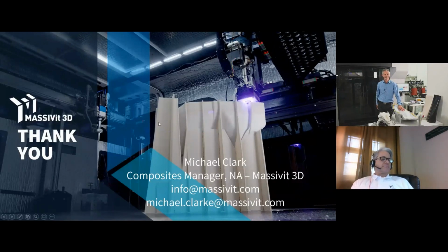Can you say anything about the tensile strength of the epoxy or its hardness, Barcol hardness? Not off the top of my head. We have them both in the tech data sheet, and we're working on some coatings that are like gel coat, and I do know that the Barcol on that material is a 92D, which is slightly harder than traditional gel coat, so it's going to have a hard tooling surface.